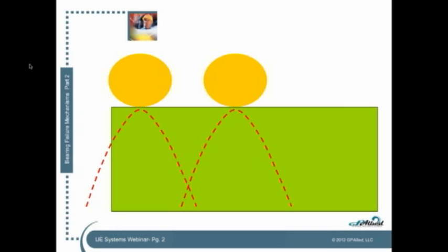And in our last seminar, we talked about how often does that happen in one day. And I showed this slide last time, but I didn't go into great detail about this second bullet point, and I'm going to this time for those of you who are interested in such things, because it bears on our discussion later on in this presentation. So here's how it works. For a shaft turning 1,775 RPMs, we just divide that by 60. We know it's turning 29.583 revolutions per second, or we say cycles per second in this case.